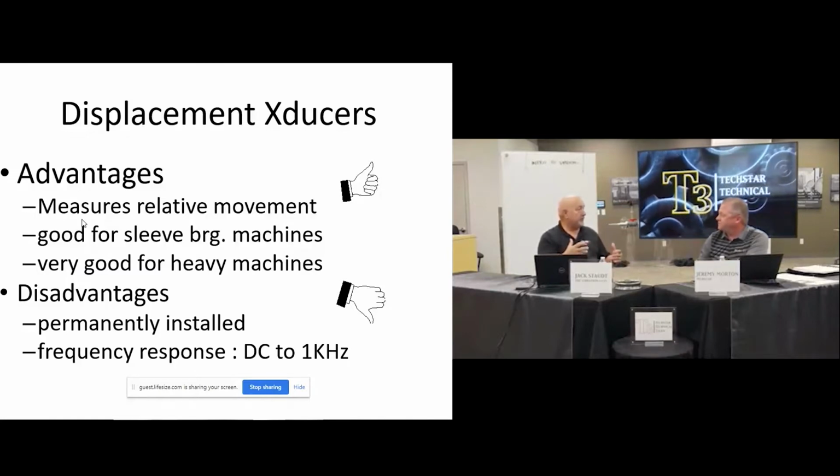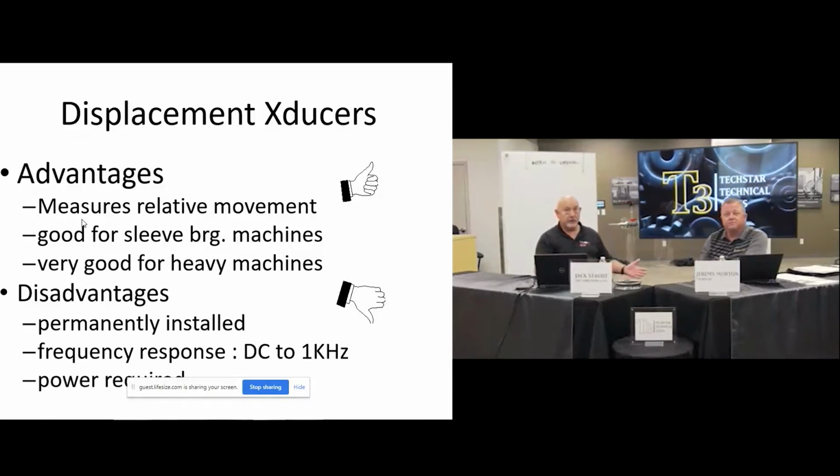If you take a case reading on it, and you look at these centrifugal compressors, some of these big boiler feed water pumps, the data you're going to collect is not going to be very accurate, because you may have to go through that much steel to transfer through to get that reading. So that's why prox probes are great on low speed machines too. That's some of the advantage with that. And power is required when you're using this. So if you have any type of glitch in the power system, then you lose what you're doing with it.